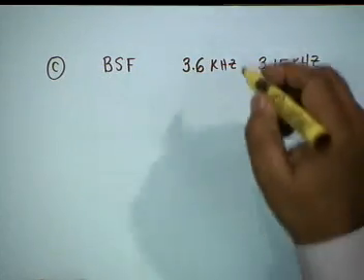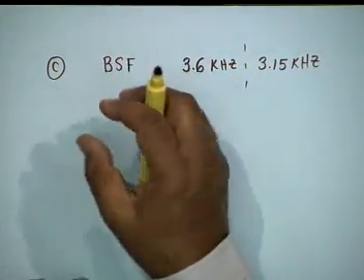You know what is done is, if you have a standard design and you encounter a new design, then first you call this program back and try to design it by using the transformation. See if it satisfies. With MATLAB you have to wait for half a minute or so. The magnitude plot will come on the screen. You see whether you have satisfied it or not. If not, then the standard design that is available is not useful to you. You have to start afresh. Okay? Is it clear? We have no control over the stop band.